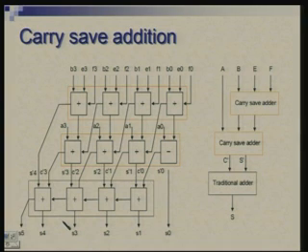So, what we have done is that 3 of the inputs are being added in the first stage itself. So, from the first stage you have sums coming out as well as carries coming out, both have to go to the next stage, right. So, the next stage is taking these sums and the carries. Carries have to move diagonally, sums have to move vertically, and the fourth input gets added here. So, AIs have got added here.